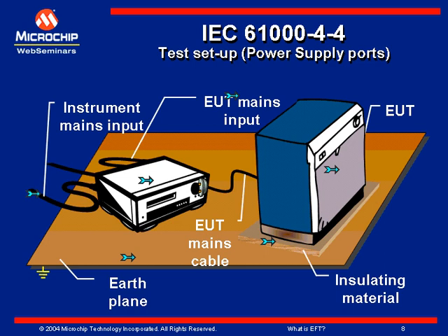The advantage of this configuration is that you may have equipment that's designed to operate at 110 volt, but you want to check a 230 volt equipment that you have designed for other countries. If you give a 230 volt input here, the equipment injects noise over the 230 volt signal, and that goes to your equipment. That way you can use the same equipment for both 110 and 230 volt testing. That's very helpful for many manufacturers who supply in various countries.